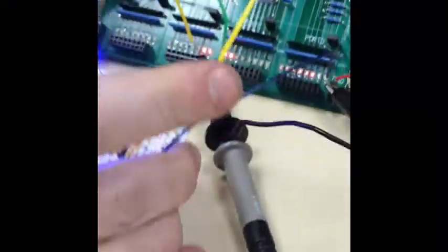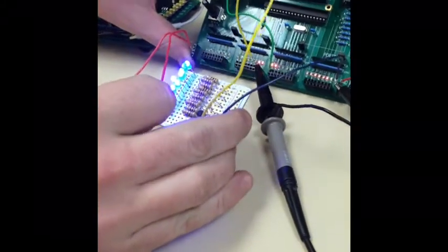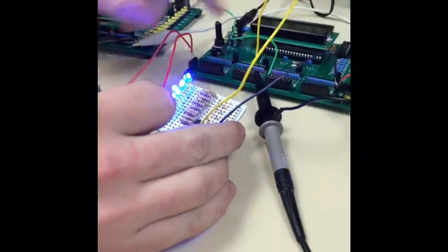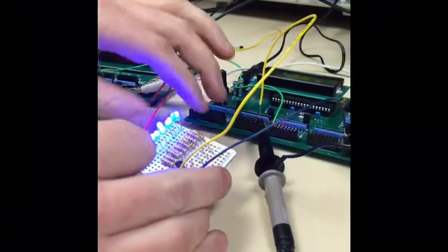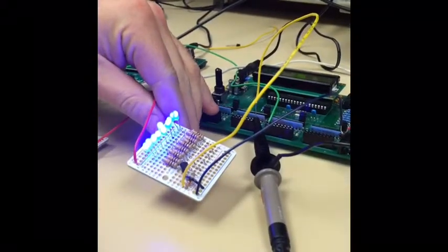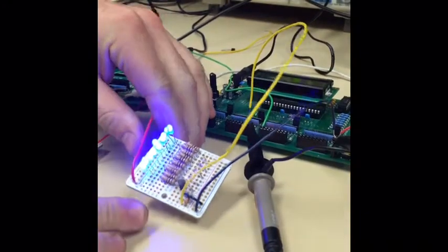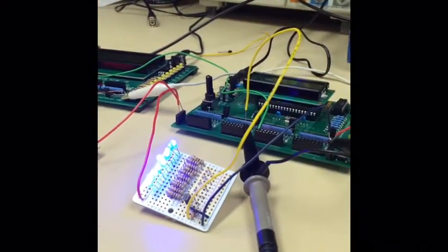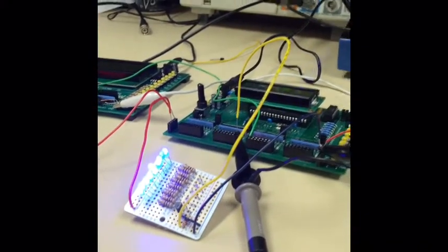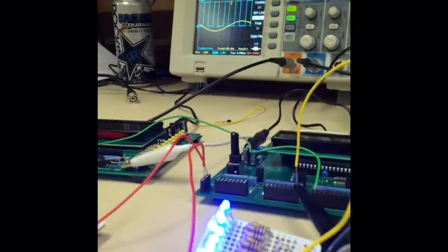So this is our LED being powered by the PWM. It consumes 1 watt of power. So the signal comes in here on the base of the transistor and then lets current flow through. So it's either off or in the saturated region. We designed that in. So to give you a demonstration with a song here, we can turn off the frequency generator.